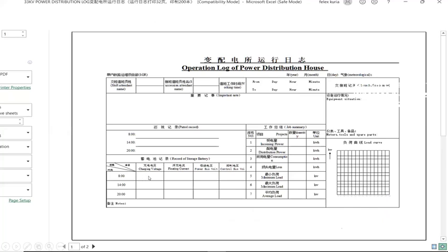And at this point, this is where we write about the storage batteries. And at this point, we usually write anything that has happened on the substation, the important notes. Maybe power was off or power was on. You indicate the time and the time the power came back.